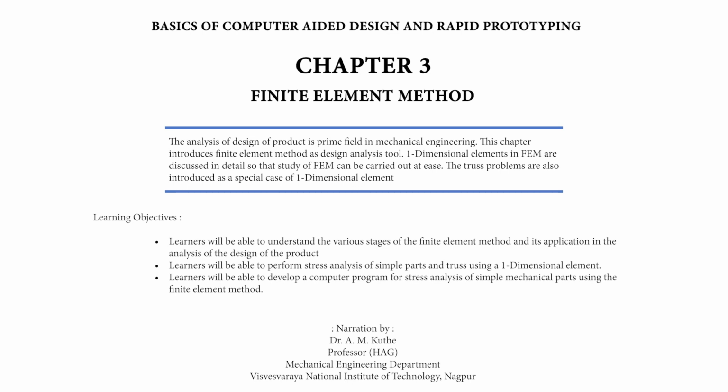Para 3.1.2 Selecting solution approximation. It is possible to find strain or stress by defining the function in which input variables will be displacement at the nodal points. The function or expression is approximate because using the value of the displacement at nodal points, the strain of any point over the element domain is found out, not directly finding the value of strain at the point of interest. The expression or the function to be selected is polynomial because it is easy to integrate or differentiate. This is the only stage of the finite element where the approximation is involved.